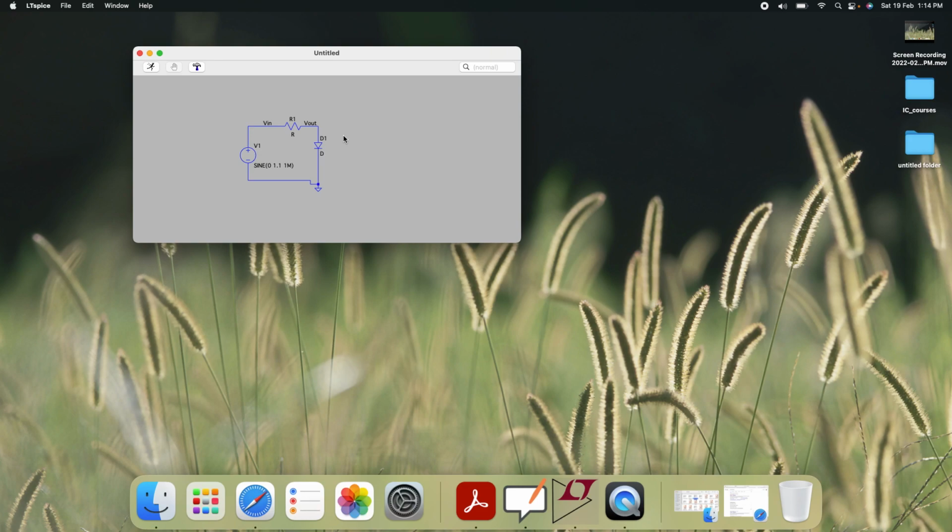Once this is done, if we try to simulate, it will not simulate. Understand, this is a run symbol. One guy is running, so it's for run. If you run it, it will not run the simulation, because my simulator does not know which analysis I need to run, like transient, AC, DC, or whichever you want. So we need to give that. If you need to add that simulation analysis, again only right click is required. Go there, and you have to give a spice directive.